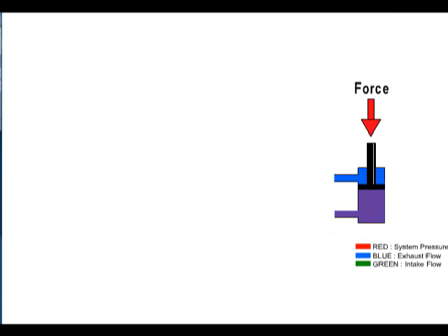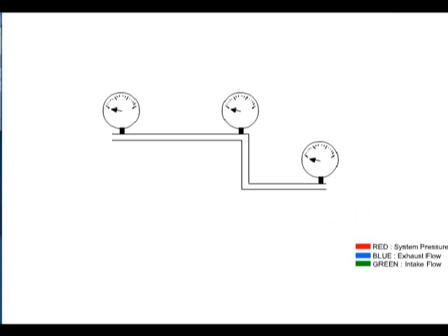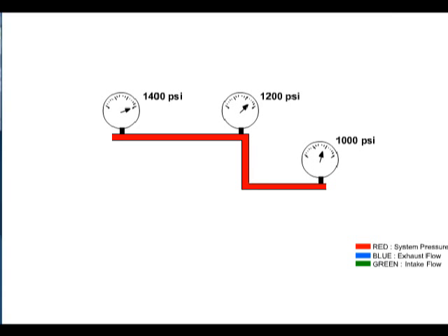This resistance to flow is load induced from the actuator and also generated as the fluid is passed through the various conductors and components. All points of resistance, such as long runs of pipe, elbows, and various components, are cumulative in series and contribute to total system pressure.